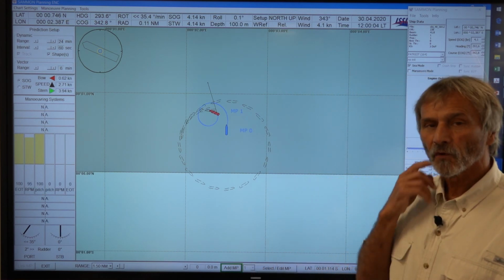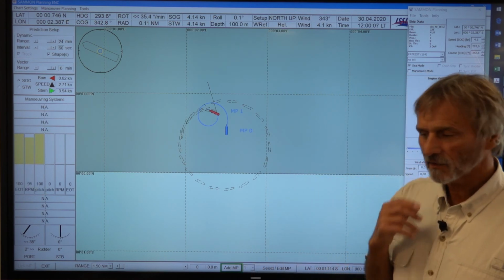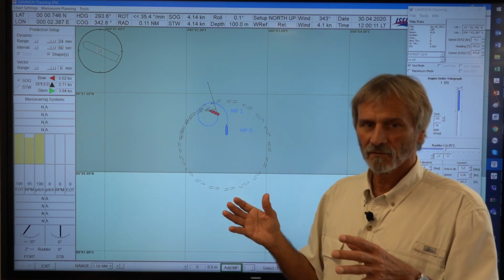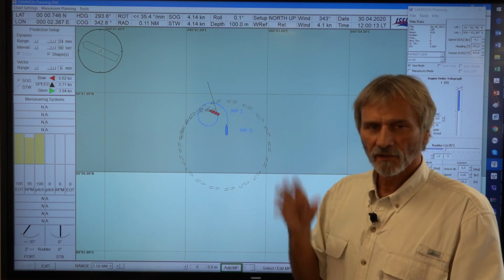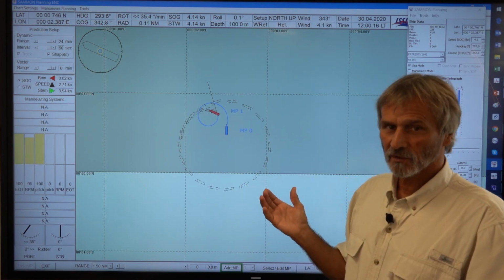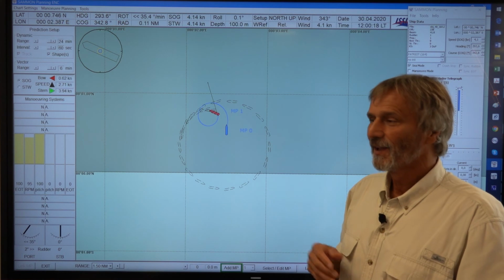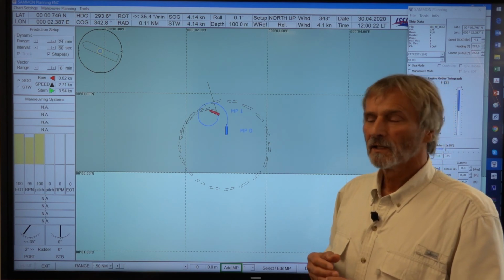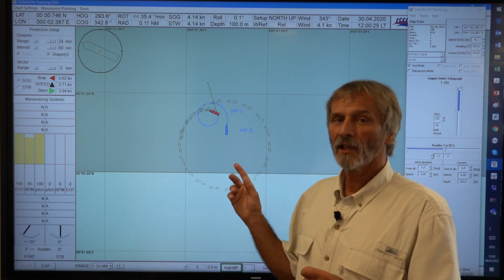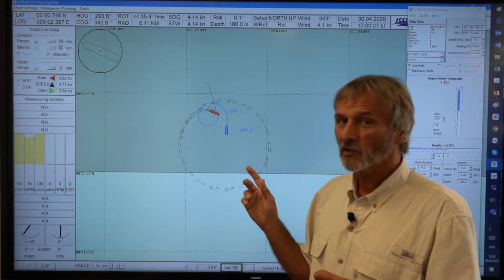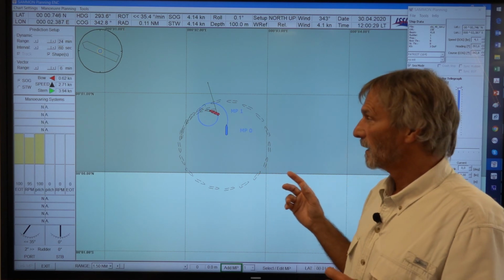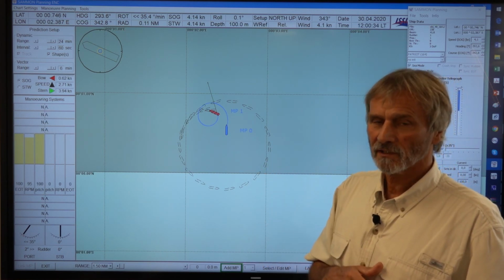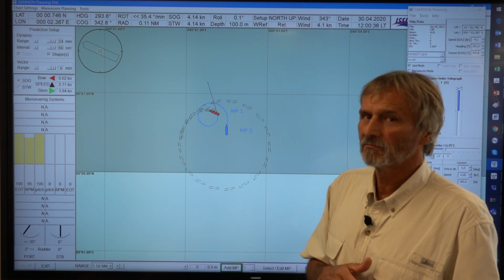And for the spiral test, you get the result that in the range of about, for this ship, 10 degrees port to starboard, there could be a turning to port or starboard, so it's not decided. And for the zigzag test, you get very high overswing angles up to 30, 40 degrees for the unstable vessels, whereas for the stable vessel in ballast condition, it's only 10 degrees.